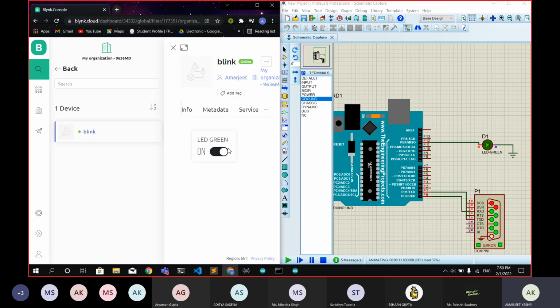You can do it in multiple ways, like you can create an analog reading parameter, and we can send the value from the Arduino to this Blynk application and create a graph or notification or any kind of terminal use. Or you can send commands from here in the type of integers ranging from 0 to 10, and according to these commands you can change these values. So this is a simple implementation I have shown you using the Blynk application. There still remains one thing, how to set this up on our mobile. I will be shifting to my mobile and presenting my screen and showing you how to set this up.